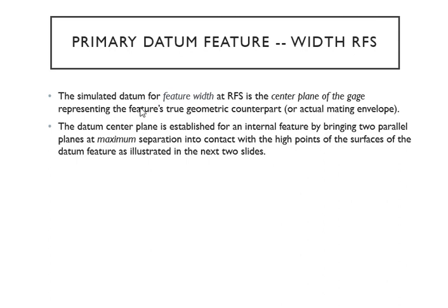Okay. So the simulated datum for the datum feature of size with your RFS is the center plane of that gauge. So the center plane is again, what is it? That's your feature's true geometric counterpart. That's your actual mating envelope.